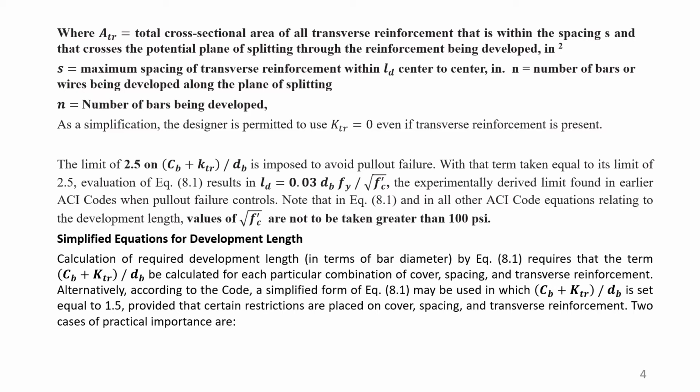And if we want to make it economic, then we have to go for the rigorous calculation. In the main equation, the development length sometimes is less. In most of the cases, the main equation gives you a development length smaller than the approximate, simplified formulas. So depending on the situation,